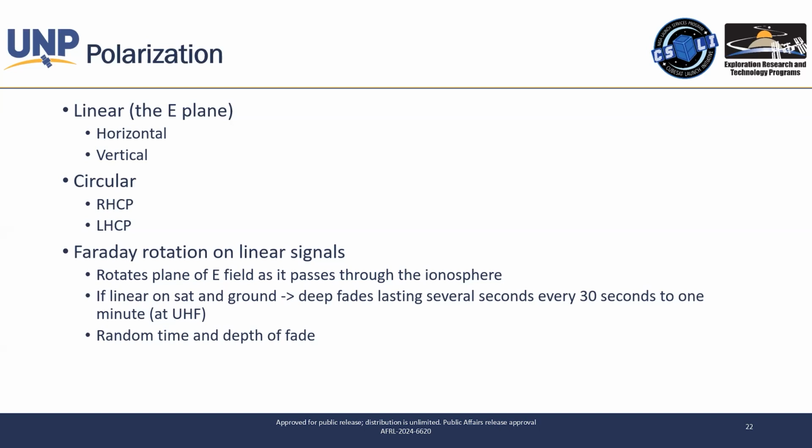If you look at the wave, it twists almost, kind of like a churro. And so you can twist it in a right-hand or left-hand circularly polarized fashion. Same idea: if you have a right-hand circularly polarized antenna, but you're trying to receive a left-hand circularly polarized signal, you're going to basically receive nothing. Essentially, the loss is theoretically infinite. It's not actually infinite, it's usually like negative 100 dB or something like that, but it's large. You're going to have a very large loss, so large that you're probably not going to be able to receive your signal.